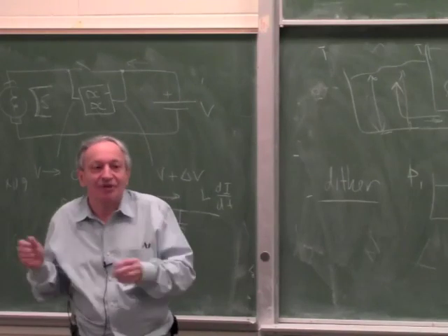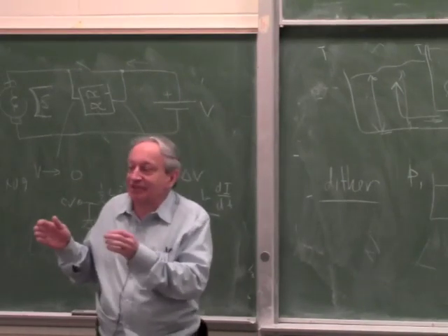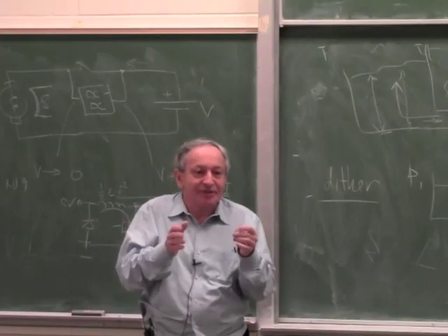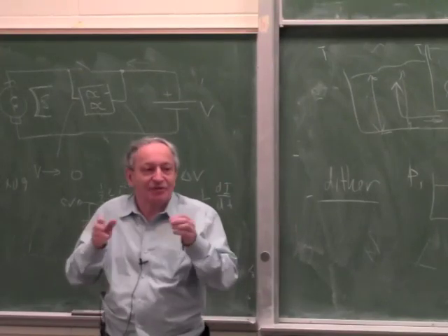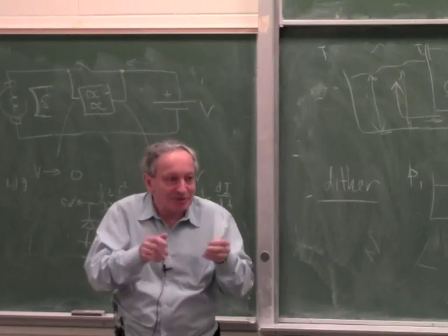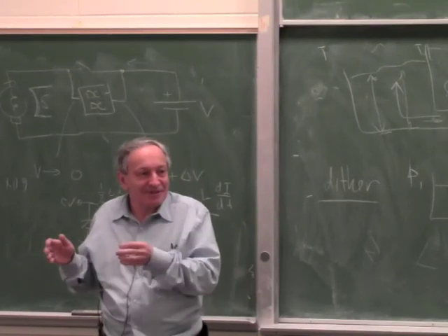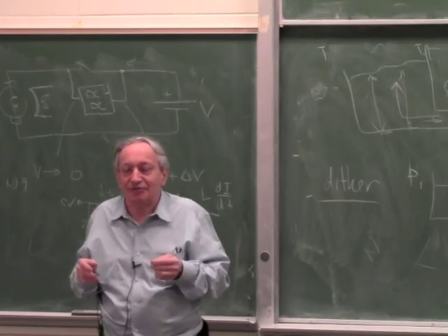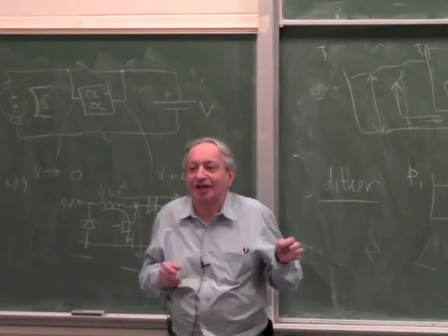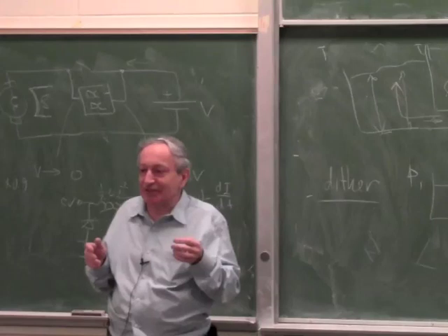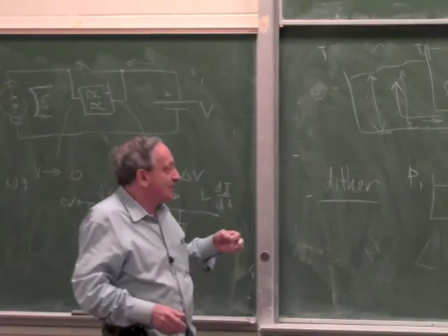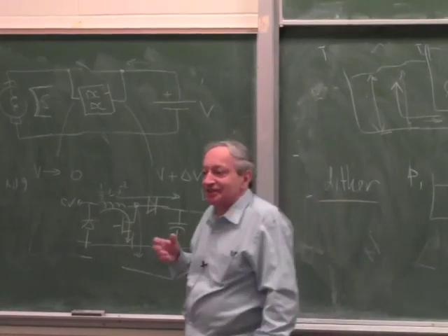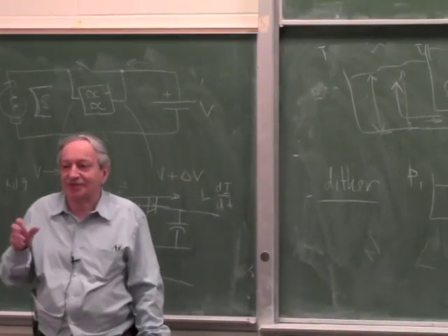If you have a piston, you want to make it go one way, you increase the pressure. You have to have a certain minimum pressure to make it start moving. Now you want to make it go backwards, you have to reverse the pressure and go a little bit below zero, right? Otherwise there is some static friction. And that's very bad for a servo, because we talked many times how bad backlash is for a servo, or hysteresis. So every hydraulic system with pistons and stuff has built-in hysteresis because of the difference between static friction and dynamic friction.